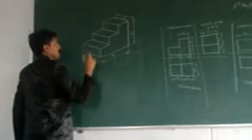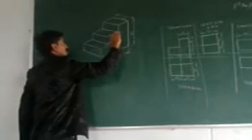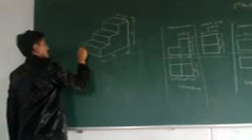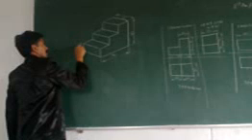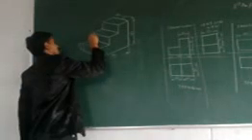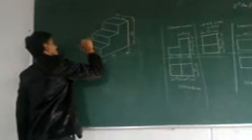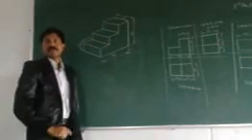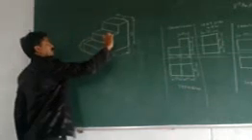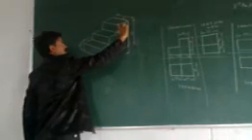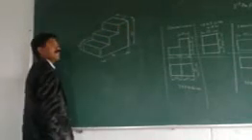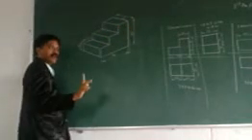So here individually this is 15, 15, 15. So this is 15 and this dimension is 30. It's enough. It is not required to give all the step dimensions. So if one is given, we imagine the same for the rest. So this is 50 and 15 and 15. Total it is 45. So 3 15s are 45.